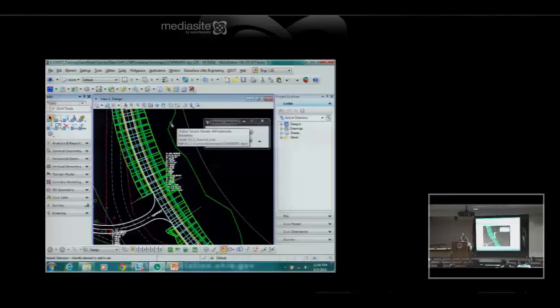And I've got superelevation defined. It's in its own design file, and it's referenced in. And my alignment itself is in its own file, and it's referenced in. So I'm using a lot of references. I know some users get hung up on all these different files, and they get all this stuff in all these different files. You don't have to put all this stuff in different files.